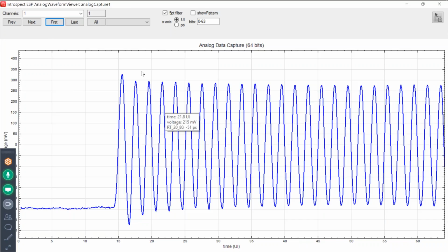frequency pattern. And the reason we show this is that typically PCI Express asks to measure voltage levels in static conditions like this. It's just a lot more accurate and a lot more consistent to measure voltages at the end of long periods of identical bits, as opposed to in varying bits as in this section here. But it's interesting to see how we could trigger the different channels to capture different sections of them.